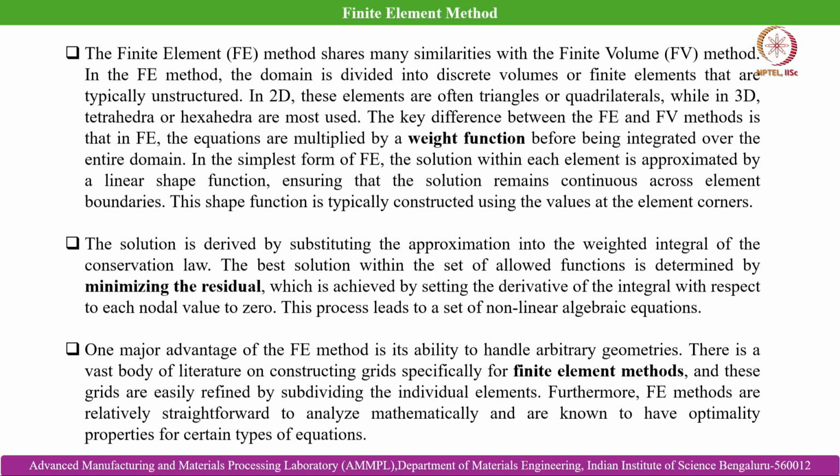In the simplest form of finite element, the solution within each element is approximated by a linear shape function, ensuring that the solution remains continuous across element boundaries. This shape function is typically constructed using the values at the element corners. Here the solution is basically achieved by minimizing the error, minimizing the residual, which is achieved by setting the derivative of the integral with respect to each nodal value to 0.